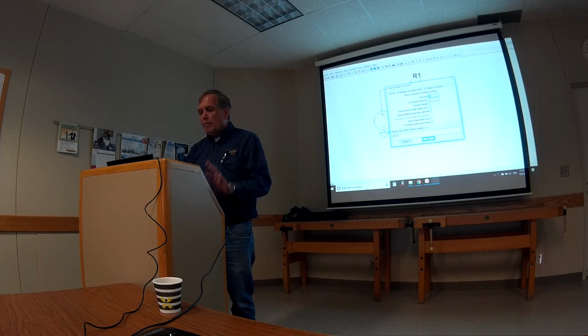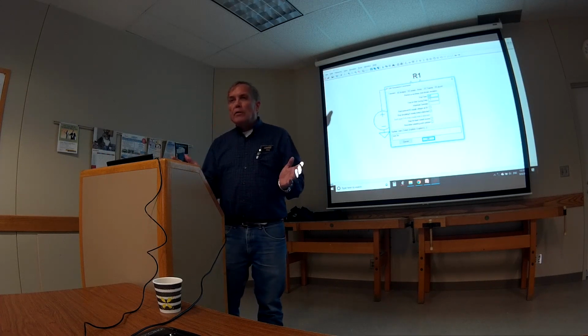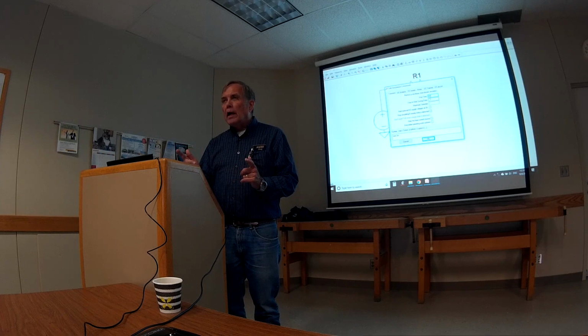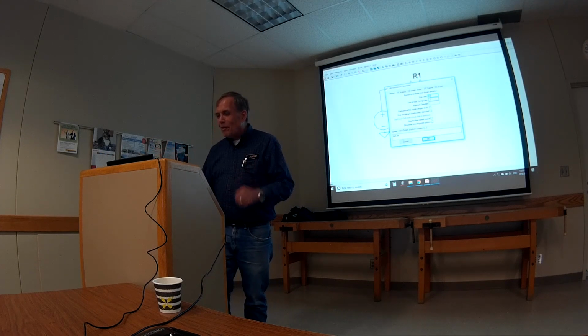By the way, in LTspice land, if you want a 2 meg resistor, you don't say 2M, okay? Because that'll go to milli every time, no matter if it's capital or small. You want to say 2 meg, and then you've got megohms, okay? Otherwise, that'll throw a lot of people.